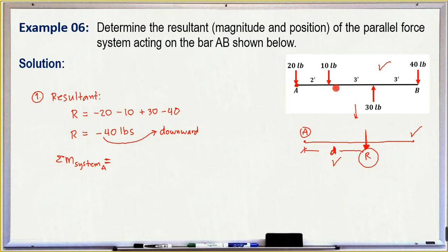We use it to determine where the totality of these four forces acts. In actual practice, you will know where to put the support. If there is a resultant of 40 downwards, you support it there, so it will not go downward and at the same time will not turn upside down or rotate.